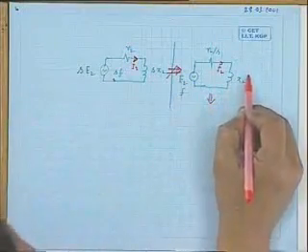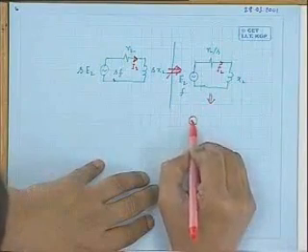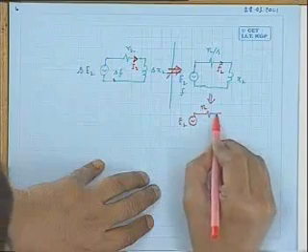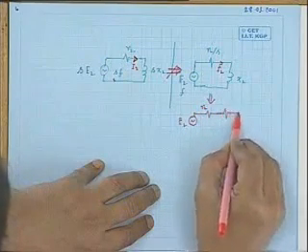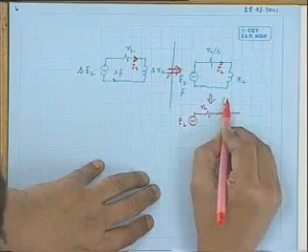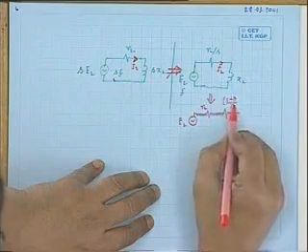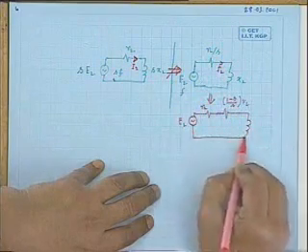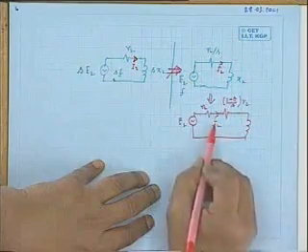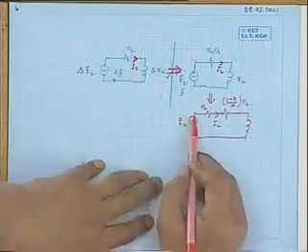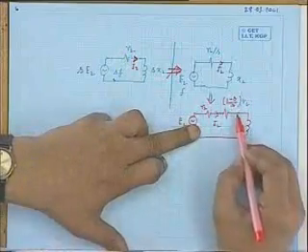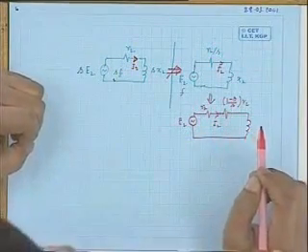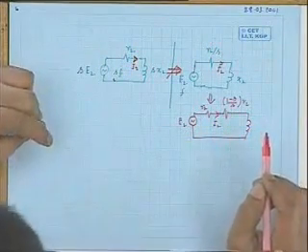Are you getting it? In this circuit, E2 is the voltage, the actual rotor resistance is R2, and the additional resistance will be 1 minus S by S into R2. I can see this resistance in two parts. Here I2 square R2, and there I2 square R2 will be the same. But another thing comes in to take into account the mechanical power developed by the machine.